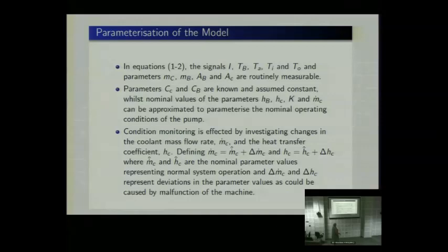And the other thing we were interested in was the heat transfer coefficient. So we were looking effectively at how the pump was managing to deal with getting rid of the heat of the block, if you like, of the pump. So we took deviations here from nominal in terms of the heat transfer coefficient. And we wanted to see if we change the valve on the water flow, would the new equivalent tell us that this had happened?